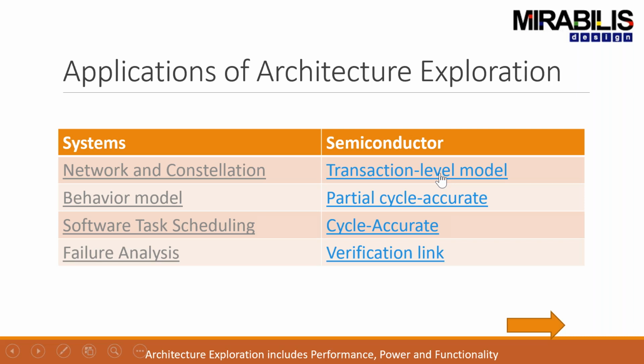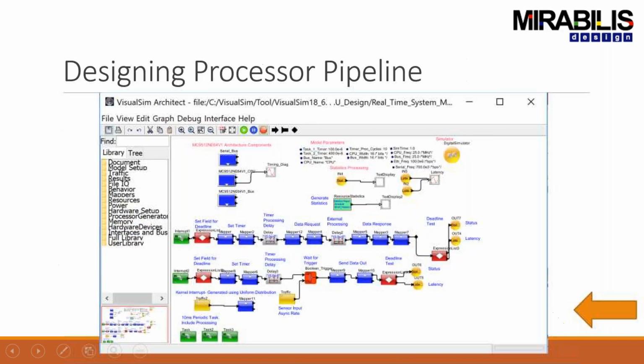Do I just use an off-the-shelf processor like a RISC-V or an ARM or an Open Power or an ARC or a Tensilica? Versus, when I do my bus structure, do I use a network on chip, or do I use an AXI bus, or a network on chip equivalent from ARM, or do I build my own proprietary bus with my own queue management system? How do I make those kinds of decisions? Which is really where the transaction level model comes in.